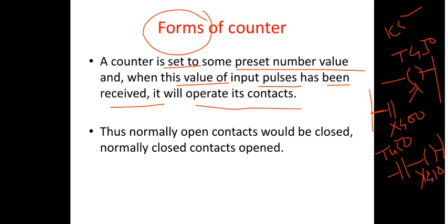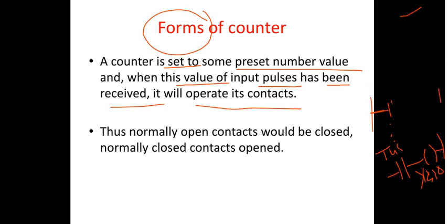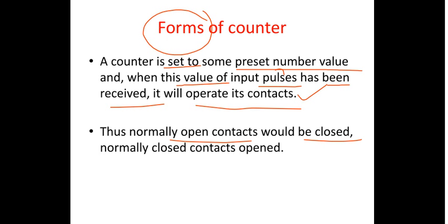Actuation you want to have by means of the counters, you would either use a normally open contact or the normally closed contact. Now let's look into the meaning of the down counters and up counters. You can see here the down counters. These are very common things which you have probably already been familiar with, right? So the down counters count down from the preset value to 0.